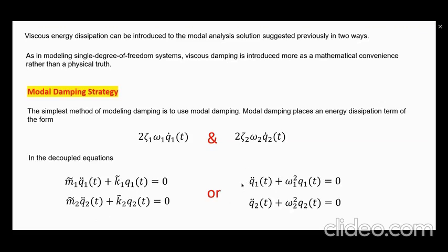of course this coefficient becomes 1, and K1 tilde over M1 tilde is just omega 1 squared. And the same thing for the second one, omega 2 squared. So these 2 equations are identical, except that we have divided by M1 and M2 and used the fact that omega 1, the first natural frequency, is the square root of K1 tilde over M1 tilde.